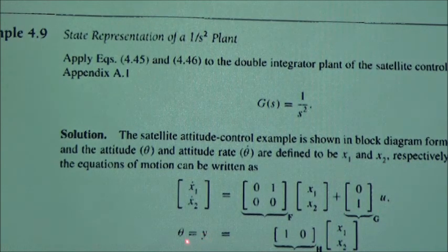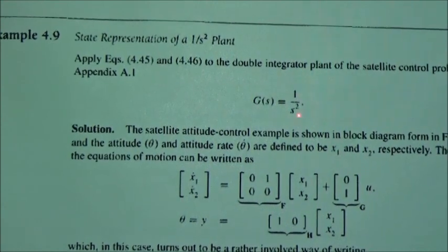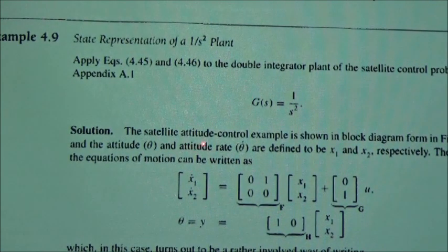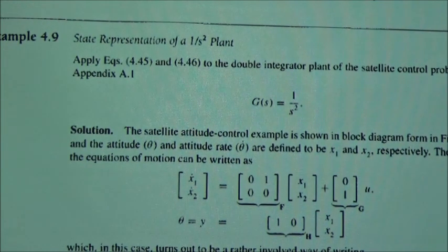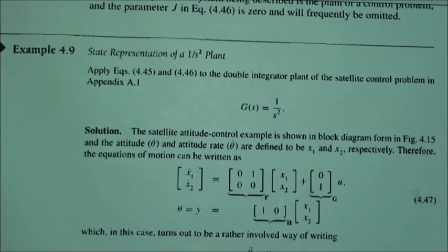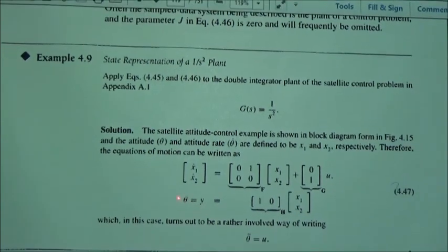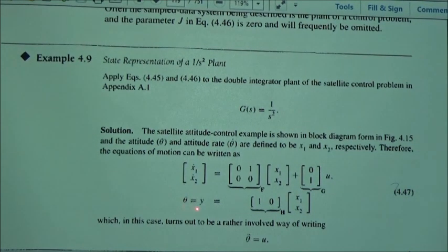And your output is theta, where theta is the attitude. Believe it or not, this is a relatively accurate model for a satellite attitude control problem. When you want to put a satellite in space, you have to apply control for all 3 dimensions of your satellite. One of them is the attitude, and this is the actual attitude control system. Your output is the attitude angle, theta. Okay, and the equation from here is theta double dot equal to u.